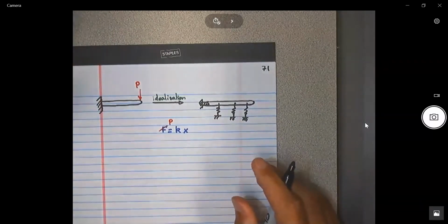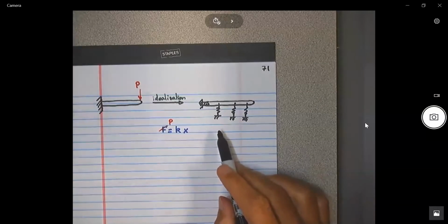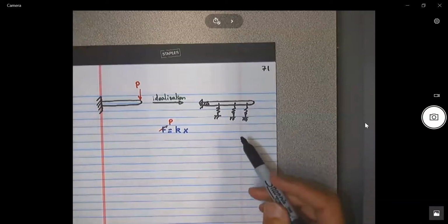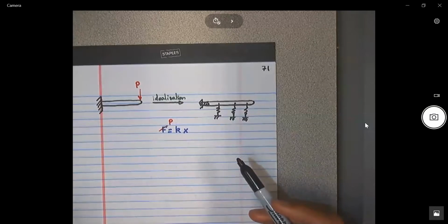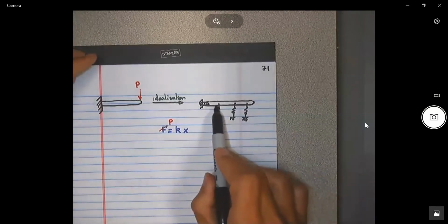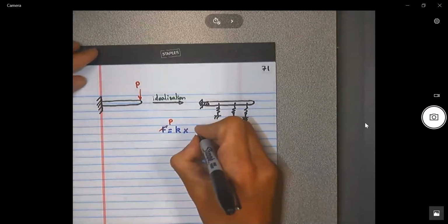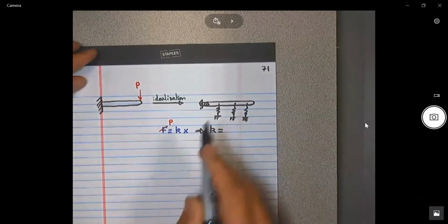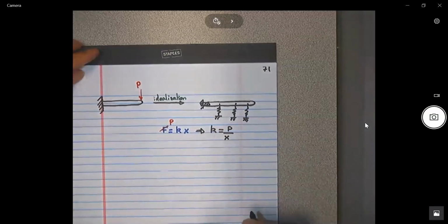So let's say, and this is the way generally people will do it, like for real wings. Do you think people in real wings are able to know exactly what is the EI, the E, the material, yes, but the I of the structure? When they do modeling, what they do actually is that they have a wing, they place a load, generally it is a hydraulic system, they press it down so they know the value of the force, and they can measure how much is the deformation, no? And they do that at multiple stages of the wing. So at each stage where they do this, they can determine the specific K for that location that will be equal to what? Force divided by deformation.